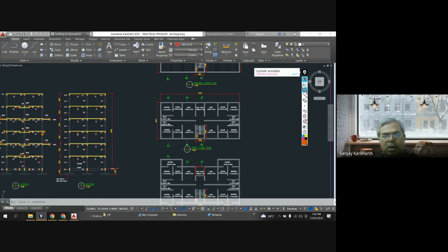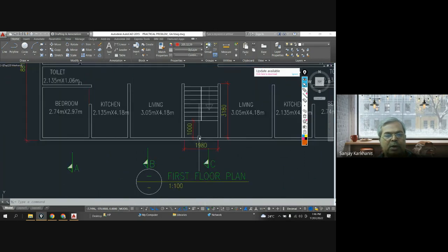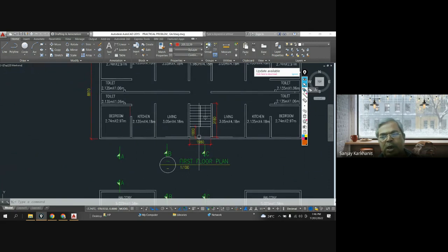Yes, from one corner. I will start the entire thing first with the stairs. So my first choice will be a column over here, then a column over here, then a column over here and a column over here. So I will have 4 columns marked right in the beginning, because later on I have to cover this, and I have to also span the staircase as per the going and waist slab.